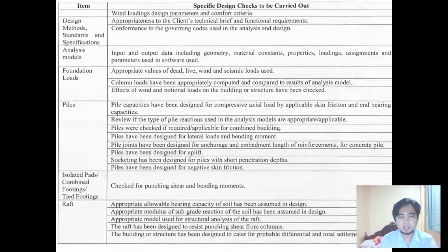So it is advisable to install piles there. So a lot of criteria that should be considered, like the friction, the skin friction, the penetration depth, the uplift forces. So anchorage, that is very important, the anchorage. And then the loads and bending moment. We should also check for the buckling, and then the pile reaction as well.